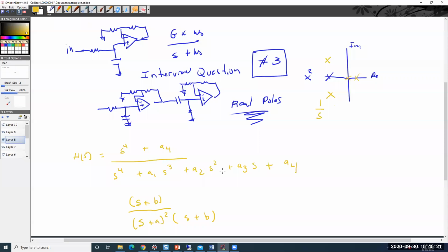And in that Python code, you gave it in pole 0 format, right? And these numbers, if you could make them complex, would actually show this behavior. But these circuits can't make complex poles, all right? Or you have a system you want to implement in op amps that it just can't do that.